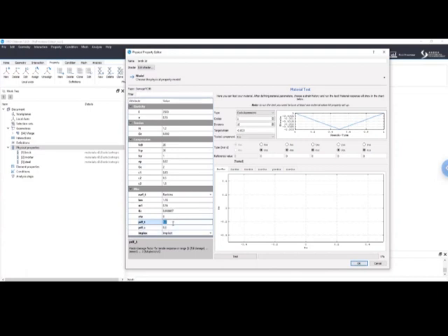Now in this case, for the brick, we want to use pure damage, as you can see here. So we put 0 and 0. Instead, 1 and 1 will be full plasticity, and something in between will be something in between damage and plasticity. Now, finally, here you have the integration method. By default, it is implicit. Otherwise, you can use the implex.